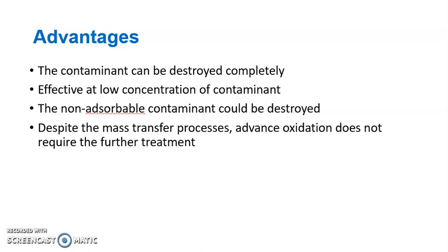It's very effective at low concentration of the contaminant, because some of the treatment practices are just working at higher concentration, but advanced oxidation process is working even for low concentration of contaminant. And that's the reason that they apply this for emerging contaminants or pharmaceutical compounds present in the water, because they are present at very low concentration in the water. But human exposure to those very low concentrations over time could have some impact on public health.